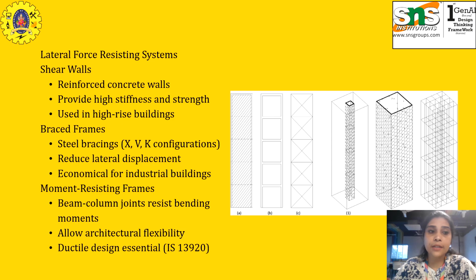So we can conclude that earthquake performance depends on ductility, construction quality, and detailing. We have to take care of irregularities in plan and a continuous load path. In that, redundancy ensures stability, and the soil, foundation, and liquefaction play a very important role. Systems like shear walls, braced frames, and moment frames are all very important. By integrating these principles, we can design buildings protecting lives even during very strong earthquakes. That's it.